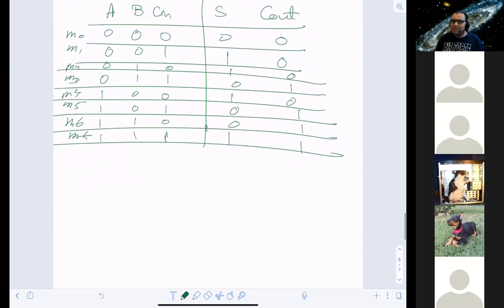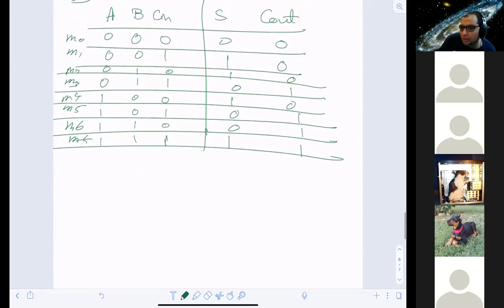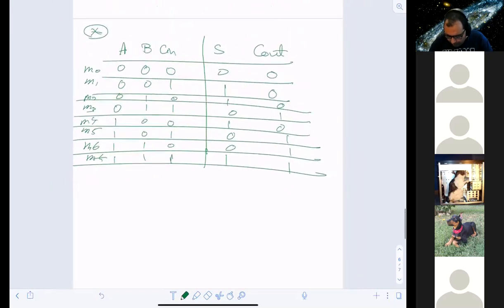If I want to build it with multiplexers, there is a way to do it, right? First of all, with a problem like this in front of me, how many outputs do I have? 2. So how many multiplexers do I need? Two multiplexers, exactly. Second, if I have an 8-state table, I can actually make it with a 4x1 multiplexer.